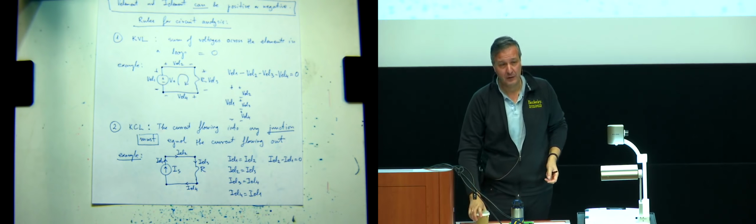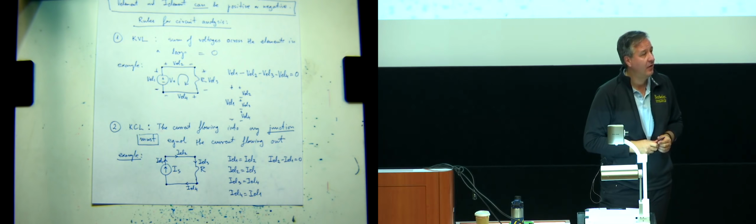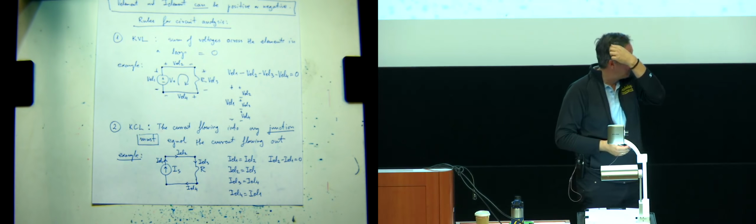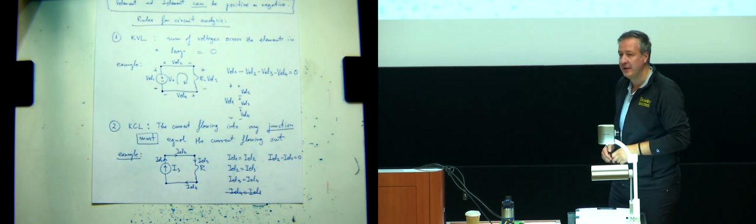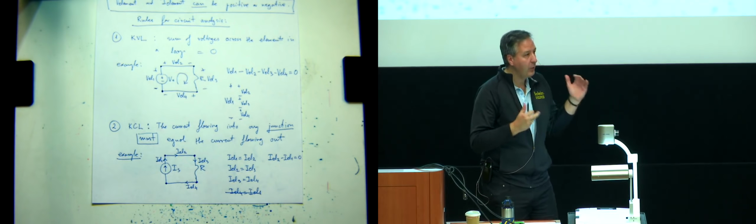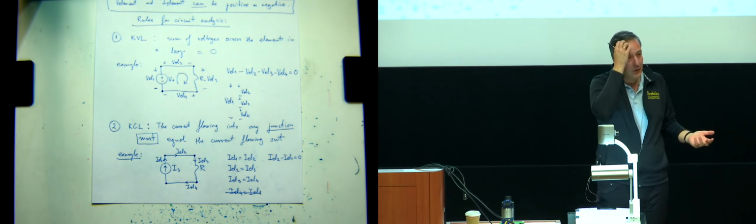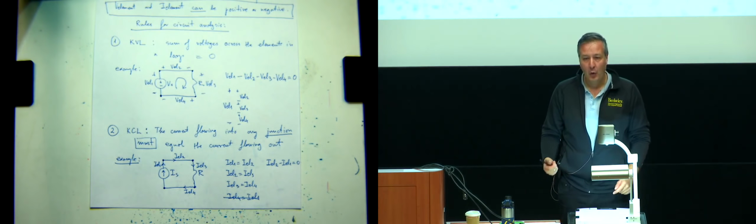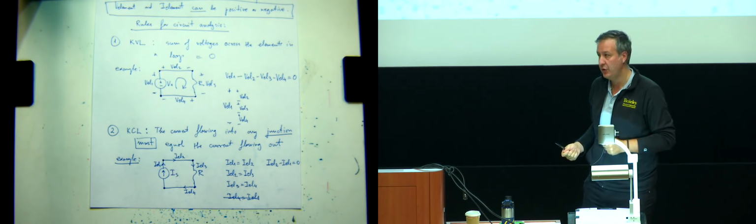By redundancy, I mean, for example, linear dependence. Yeah, I can do mathematical manipulations on the first 3 equations to get the 4th equation, right? So I don't really need it. We're all about efficiency, so we only want to specify as many equations as are needed to actually solve something. This one doesn't help us, right? So when we do circuit analysis in later steps, we will keep this fact in mind: we don't have to look at all the junctions in the circuit, but we can look at all but one.